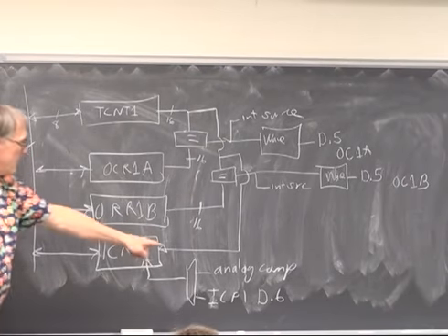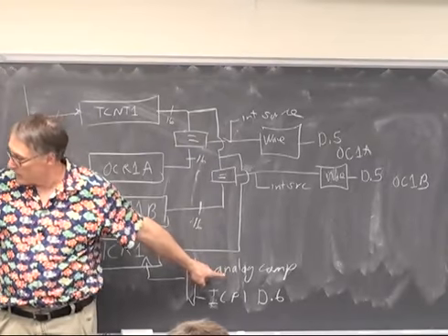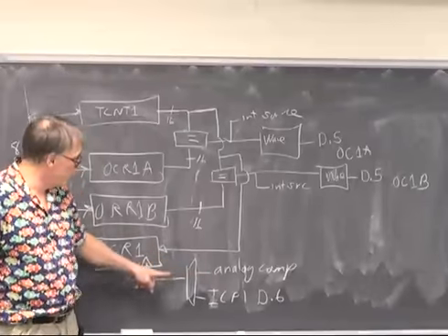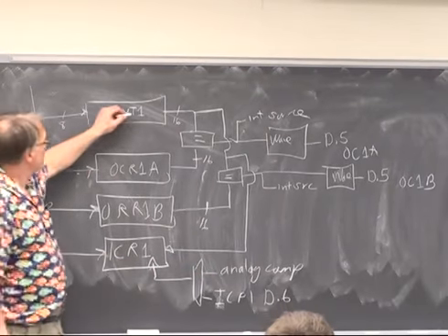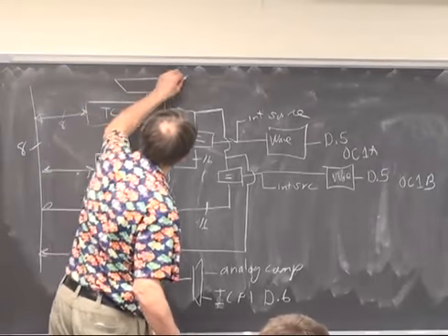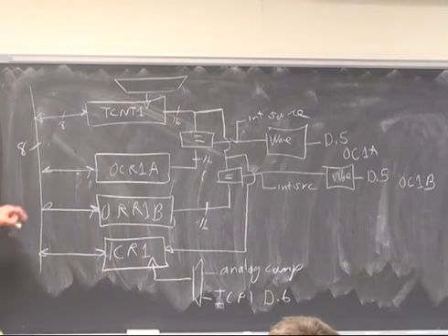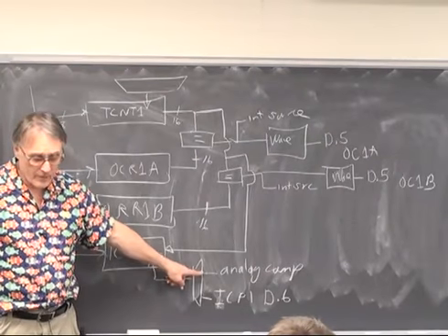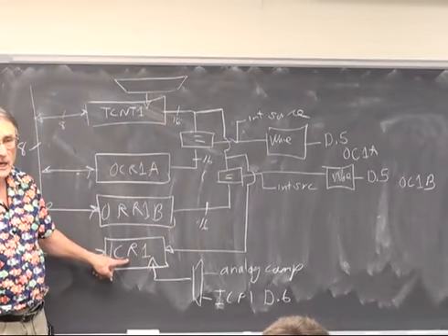So, this gives us a way of connecting a transition on the analog comparator to the input capture register. Timer 1 is counting away at a rate which is dependent upon yet another prescaler and multiplexer. When a transition occurs on the analog comparator, the value in TCNT1 is snapshotted into ICR1.